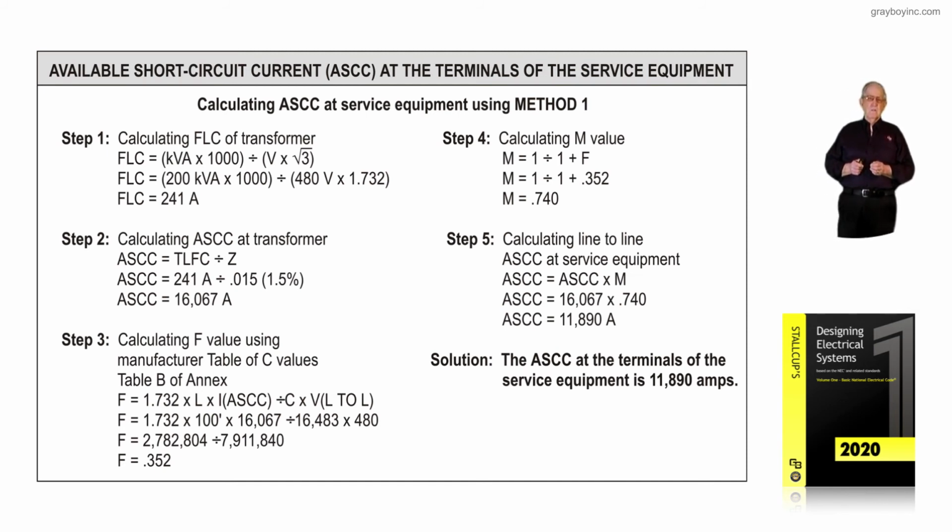If you could purchase it, you could use a 15 kA system, and that would handle the available short circuit current. Now notice, this can be done by an electrician in the field. And if you go online and order the Stallcup's electrical design book, those tables are there.